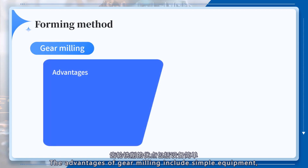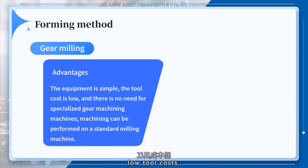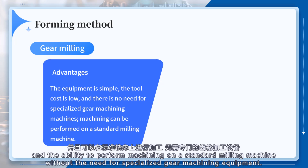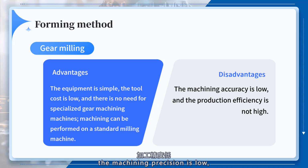The advantages of gear milling include simple equipment, low tool costs, and the ability to perform machining on a standard milling machine without the need for specialized gear machining equipment. However, the drawbacks are also evident. The machining precision is low, and the production efficiency is not high.